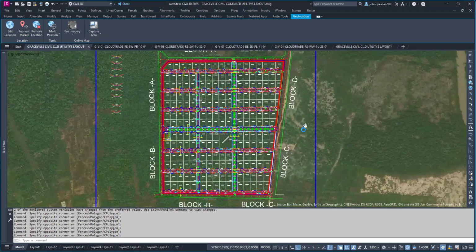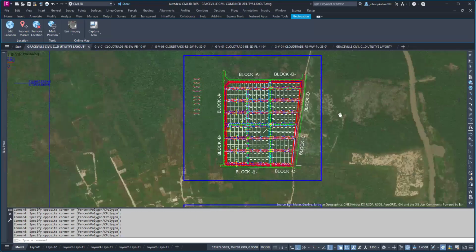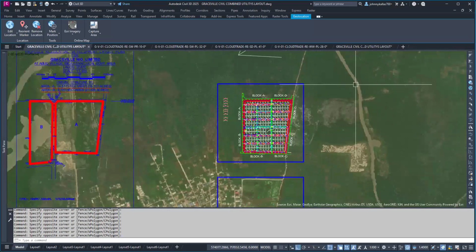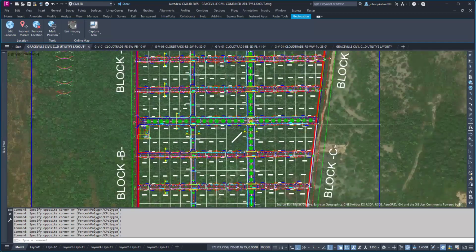The sand, we are going to remove it from the canal. So we are going to do a soil test for the sand, to be sure we are removing pure sand, sharp sand. Then after that, if you want, we can do a soil test for this road, for example, in 2 or 3 places for each road, so we will have an idea what we have under the ground. Exactly. We can do this exercise. Sure. Okay. Thank you.